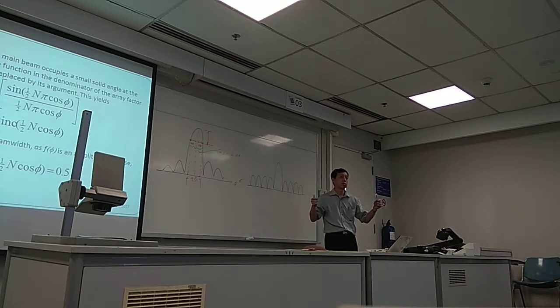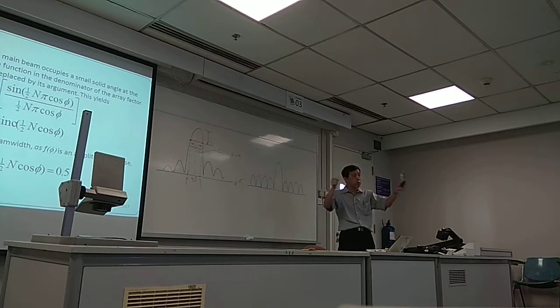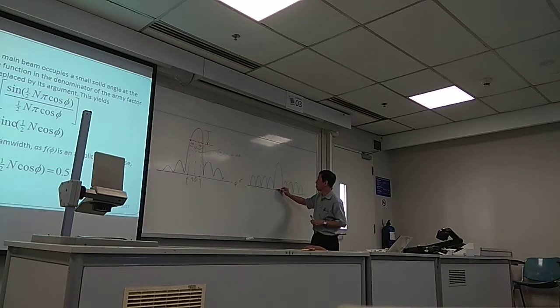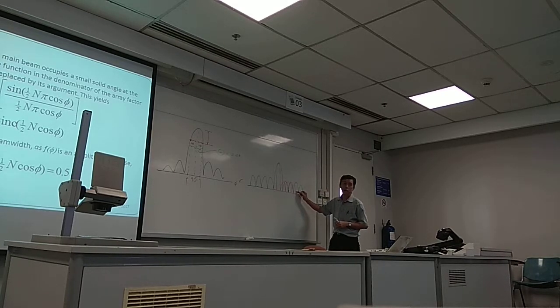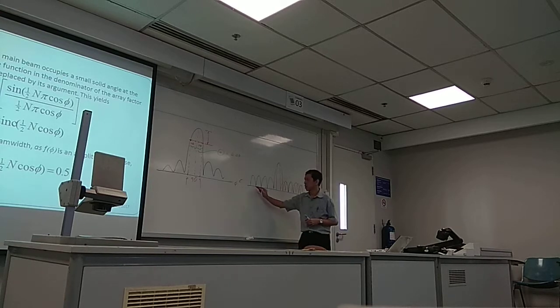Of course, what you do is you reposition all the antenna elements, and you can remeasure the array beam pattern. You'll find that the beam will become sharper. You follow? Now, you will not see the side lobe having a grating lobe appearing at this direction.